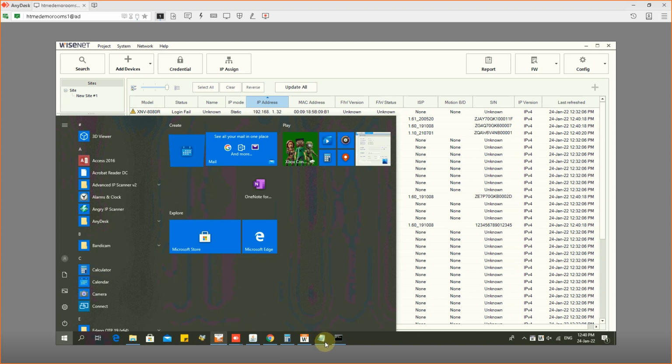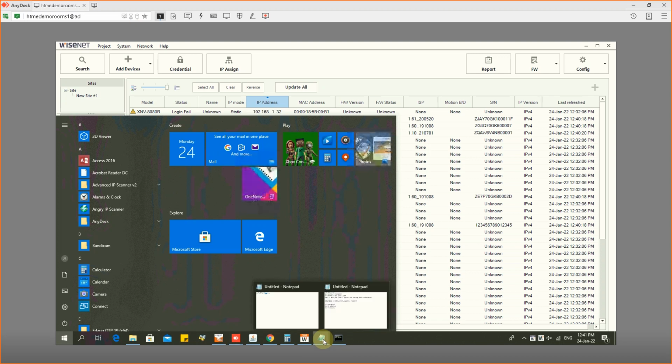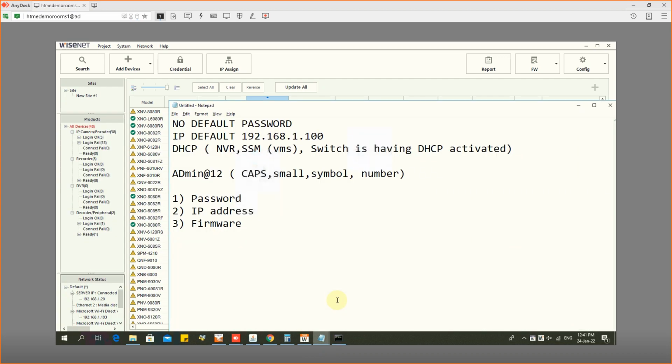after you fix the firmware, you update it. It is important to update. Please do not skip that step because your NVR may be new and the camera is old. The new NVR and the old camera, maybe some video may work, some feature may not link properly. So we would have updated the camera.